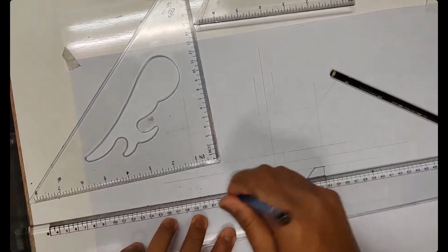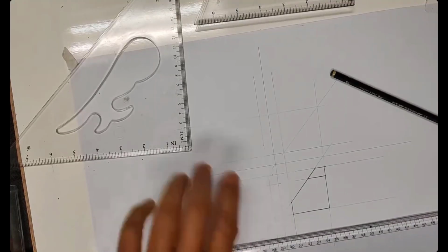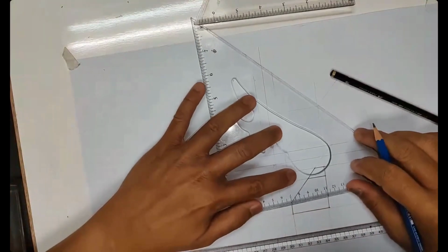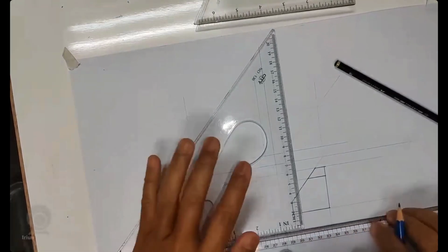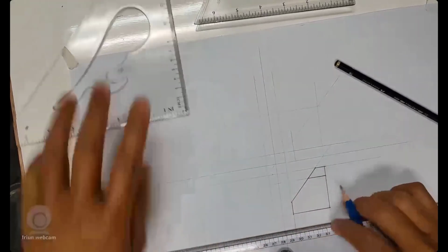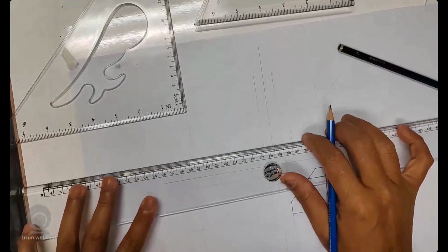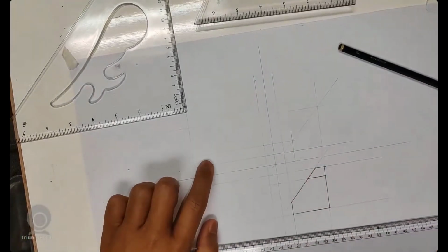So you bring it into the front view. I bring the projection to see this part you see on the side view. And also if you look on the side view, we have a 10 segment there. So I put a 10 here. I measure 10. So they are using 4H for construction line. So this will be the 10. So I bring it here. We have 45 degrees. So I bring it there. All the intersection line will assist you to draw on the top view.